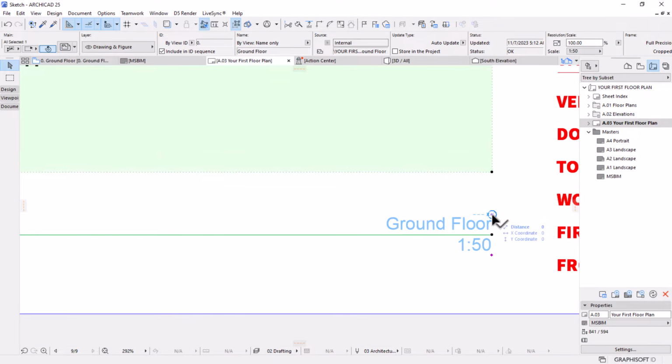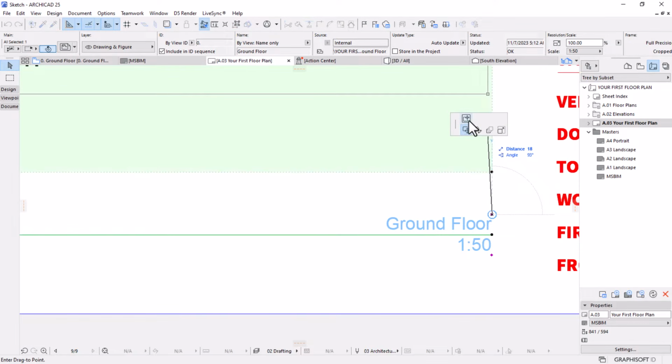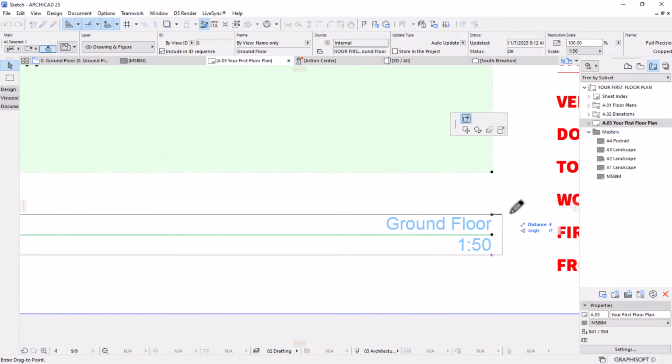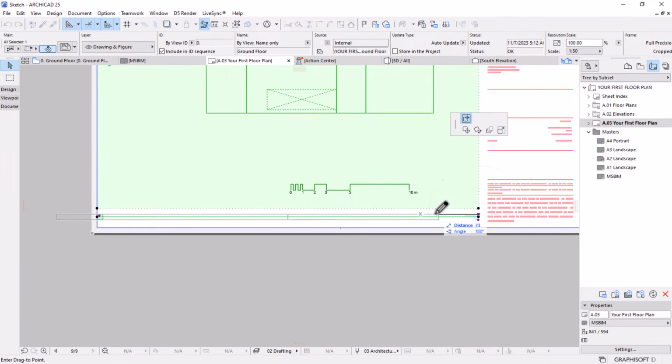So I would start by taking this text by clicking on this hotspot, this purple hotspot, and then let's change the tool on the pet palette. Instead of a drag, to move sub element, because these are sub elements. So I'm gonna click on this and then it will move. Okay, you see now it moves. What moves here is the entire drawing title.